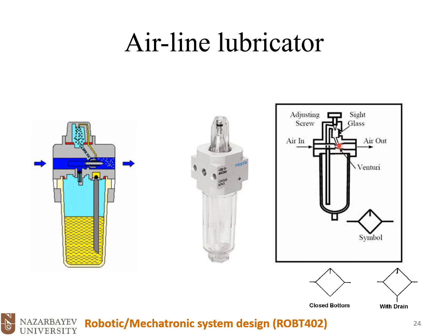Now we have a lower pressure here at the neck of the Venturi, and then it will create some sort of suction. So we could suck the oil from this feed pipe. Why do we have a suction again? Because at the neck of the Venturi we have lower pressure of the air.